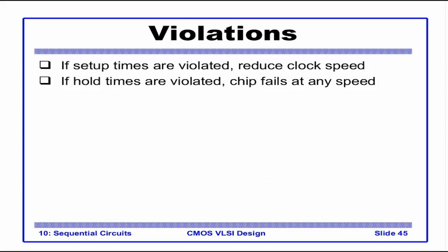So let's look at what happens if setup time is violated. We saw that the setup time imposes a maximum performance limitation on the design. If setup time is violated on a manufactured chip, you can actually reduce the frequency and still check if the chip is working. But if the hold time is violated, you can do nothing. The chip will fail at any frequency, since the hold time constraint, the min delay constraint, is not dependent on the frequency.